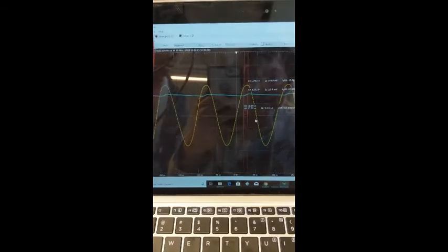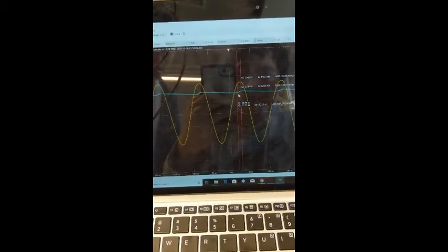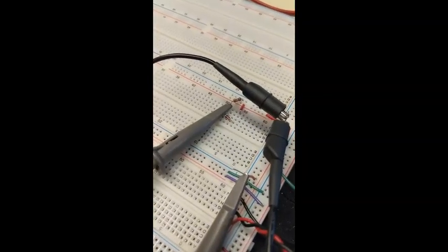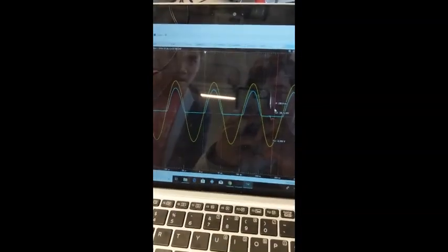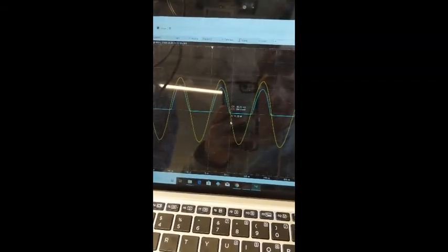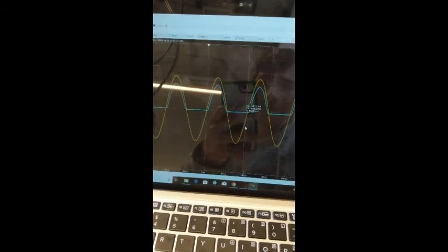This is our waveforms. The ripple voltage is the voltage from the bottom to the top. This is our circuit without the capacitor, which turns the circuit into a half-wave rectifier, which does not allow the negative voltages to pass because of the diode. If we decrease the amplitude to 1 volt, or 2 volts peak to peak, we see that there's a bigger effect due to the inherent 0.7 volt drop from the diode, from a smaller input signal.